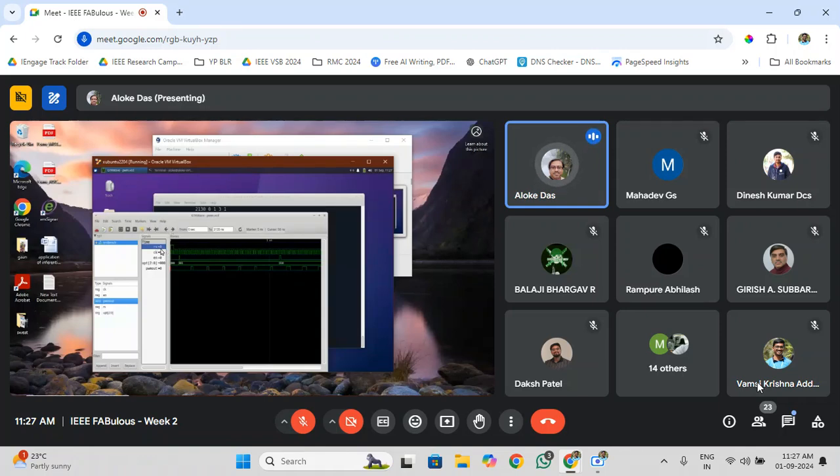You have to do reset because all these designs are created with flip-flops, and if you don't reset a flip-flop, it remains in an uninitialized, unknown state, that can give you wrong results. And so the reset signal is there. So after that, everything got reset.